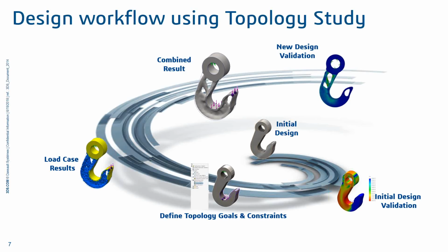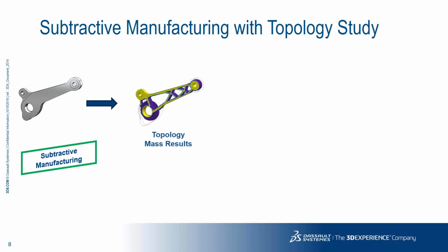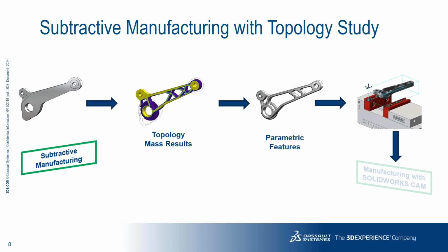And of course, at the end of this workflow, it's always a good practice to run another validation to ensure that the results that you're getting from the topology study are within the design requirements. It's able to withstand the forces that will be applied to it.